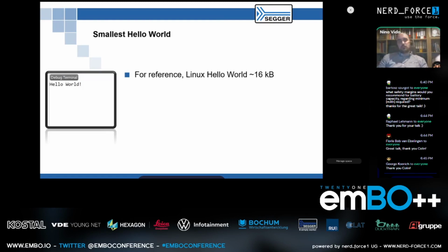And this is something that we don't really need or require on an embedded target device, as we usually use other interfaces to direct the printf stream. And this is where it's also important again to have a library which has embedded systems in mind, and where the best is done to avoid having bloated code for something as simple as a printf.